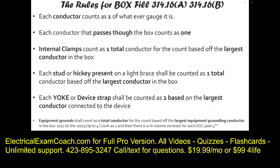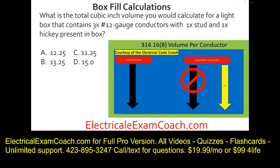Let's get to it. What is the total cubic inch volume you would calculate for a light box that contains 3 12-gauge conductors with 1 stud and 1 hickey present in the box? For this one, we're going to go to table 314.16(B). We know that each 12 is 2.25 cubic inches. Now let's count our conductors.